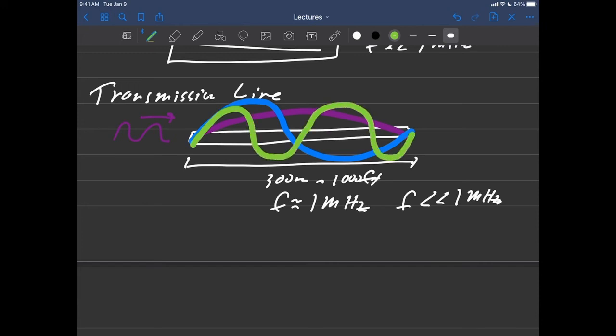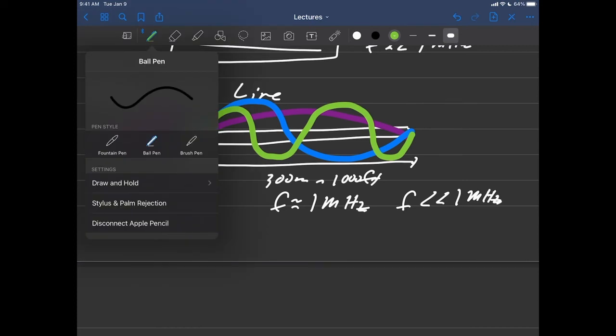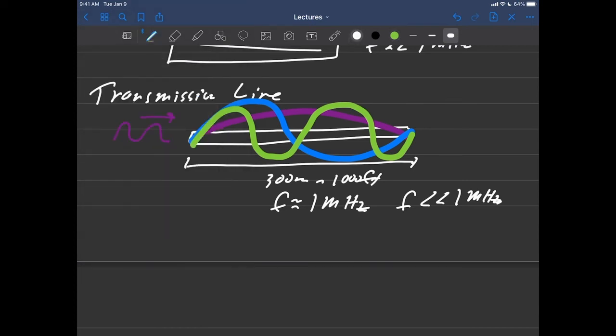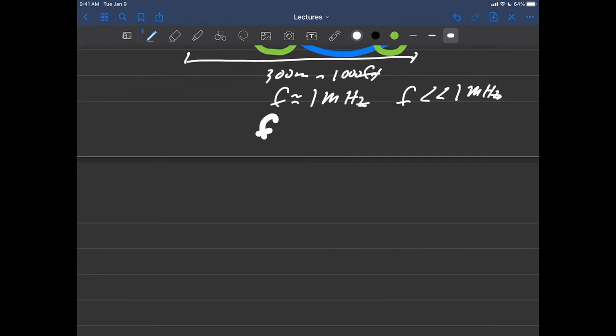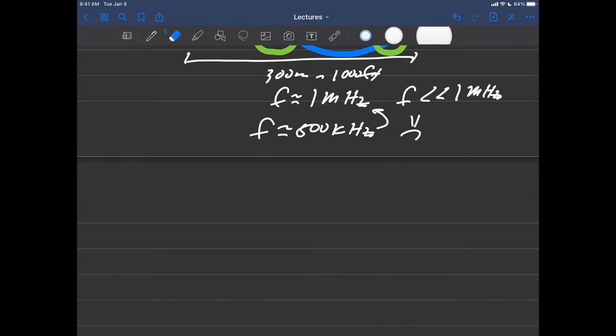In the circuit, what I tried to do is, as we were running the circuit, I was probing around looking for resonances, and I did see some odd behavior. I think you might have seen them as well. I definitely approached some frequencies near about 500 kilohertz, which is about halfway there, and that was just a bad thing to do. You want to stay away from that. Remember, I wanted all my frequencies to be much, much less than 1 megahertz.